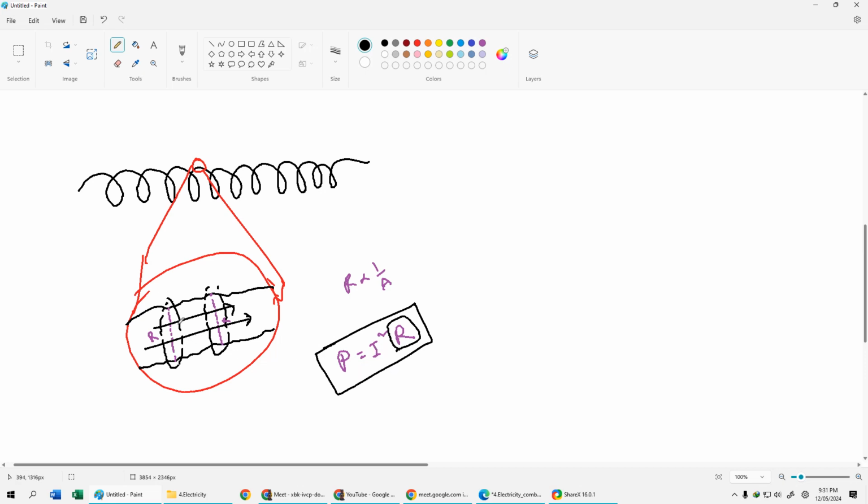As a result, every small section of the wire that has a little bit of small cross sectional area is going to heat up really fast, and it is at those locations the filament lamp might melt and break apart. That is going to destroy our highly costly equipment, and for that reason we do not want that to happen. That's why we initially provide a very small current, thus uniformly heating up the entire filament coil, and slowly gradually increase the current to 12 ampere so that the whole thing is not burned out at a random location.